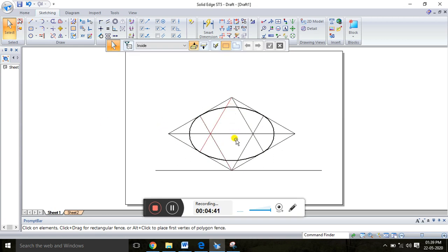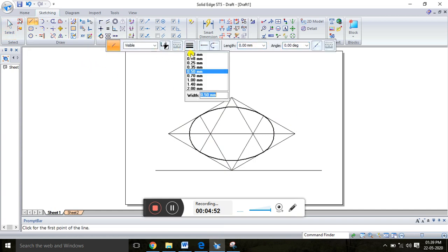So first we construct the bottom face of the cylinder, and it is of height 30 mm. So first you have to place the center. So from here 30 mm. So this is the center. Okay, so the thickness is 30, type 30 and place.